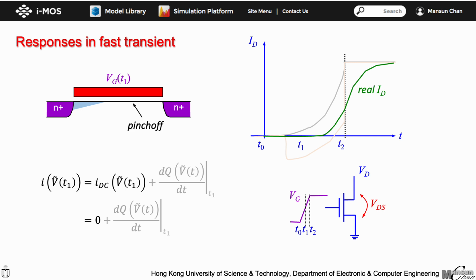For the charging current, we assume that there is a high drain voltage at the MOSFET. The MOSFET was initially operating in the saturation region. In that case, there is a pinch-off region at the drain, cutting off the drain terminal so that the channel charge is mainly coming from the source. Therefore, the charging current from the drain terminal is also 0, leading to a 0 drain current.